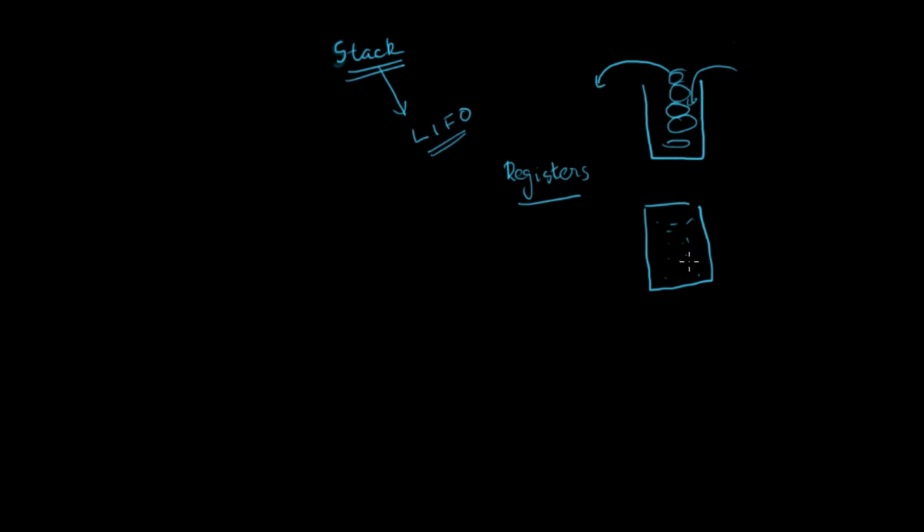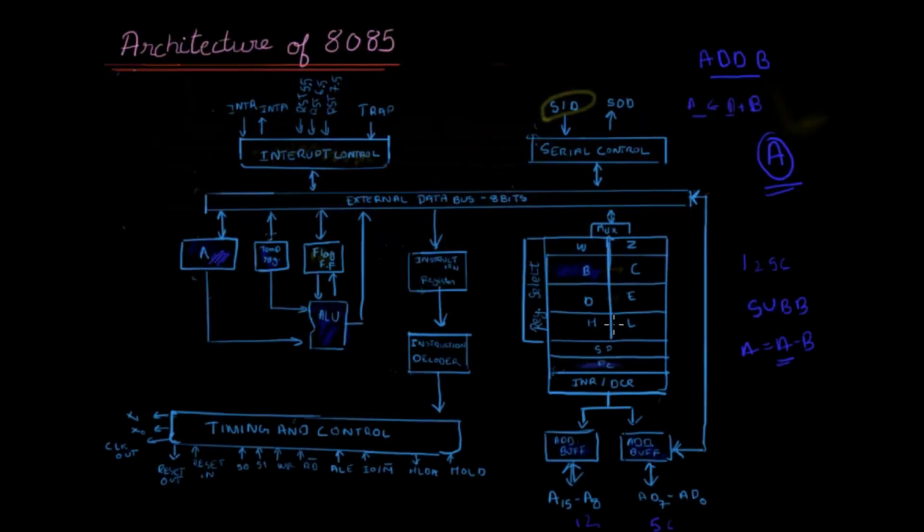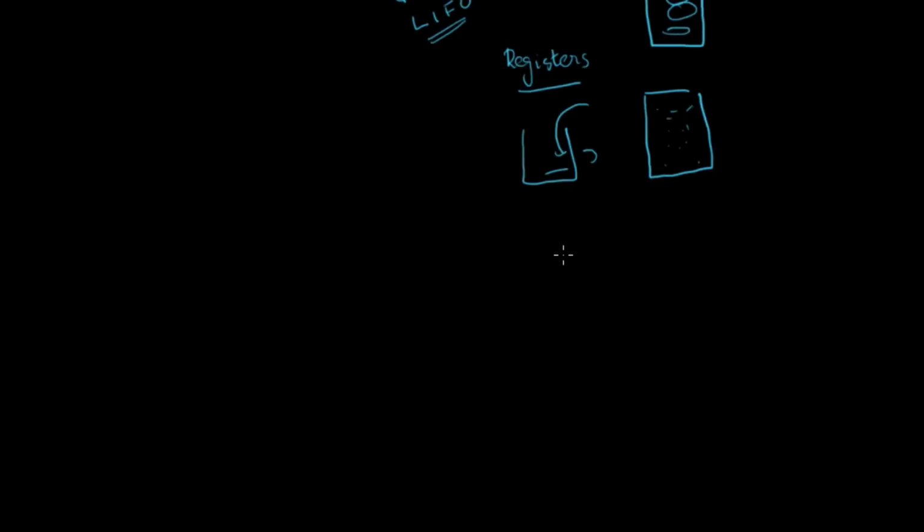So what we do here is have an organized memory allocation process in which the data is first stored here, then we increment a particular pointer called the stack pointer. That is what is seen over here, this pointer, the stack pointer. This is incremented and the next value is entered. Then it is incremented and the next value is entered. That is the function of a stack pointer.